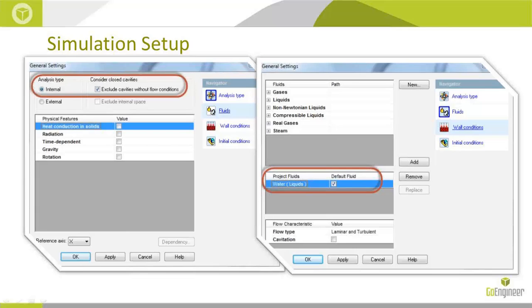So all the solids in SOLIDWORKS Flow Simulation are rigid and do not move or rotate. So they don't translate or rotate. A very common problem that we solve, though, is something like a fan or a turbine spinning. So what we can do is define rotating regions of fluid in our model around those objects and get the same relative effect.